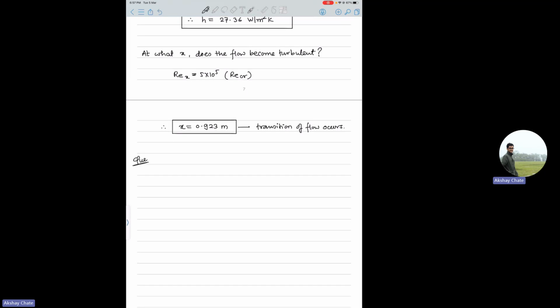So typically, when we studied extended surfaces or fins, there we assumed, in the governing equation, there was an m multiplier, right, which was under root hp by k, and in those problems that we solved, the h value was given.